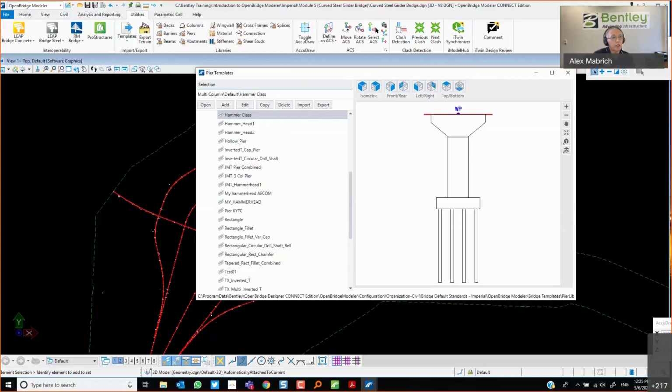So here, for example, I got a question that says that the variables in the template need to match the roadway file variables to super elevation. No, it doesn't. I will try to place it and see if it works, but I think I have a super elevation file. It doesn't need to be applied. It doesn't need to be the same. No, for the super, right? So I got the two templates ready.